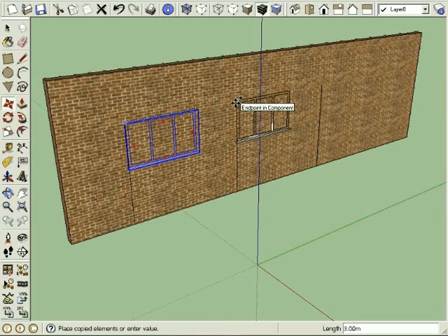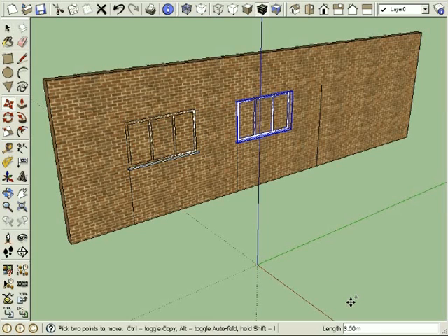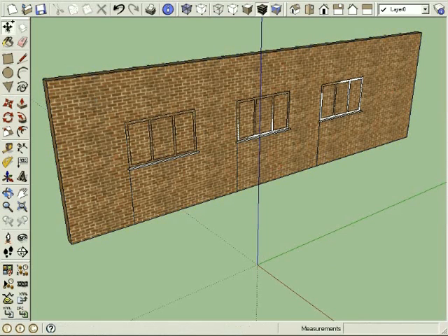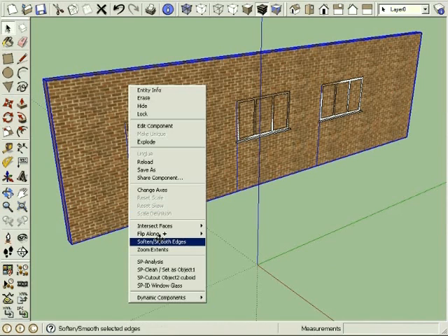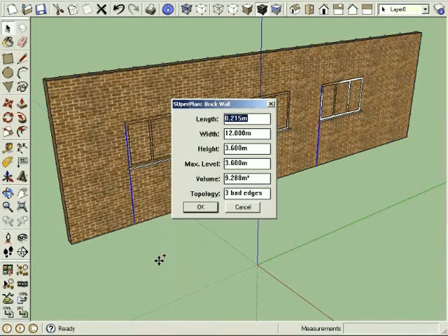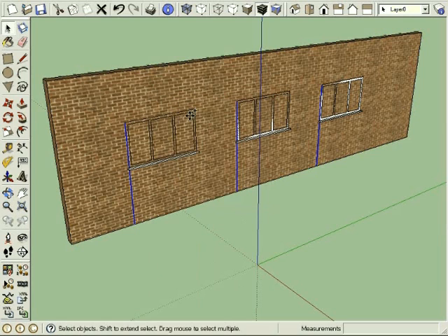In this example, 3 lines have been marked on a wall to indicate the required location for 3 windows. On placement, each window becomes buried in the wall. Note how analysis of the wall highlights the lines as superfluous edges, and selection of this wall as the first object automatically removes these edges.